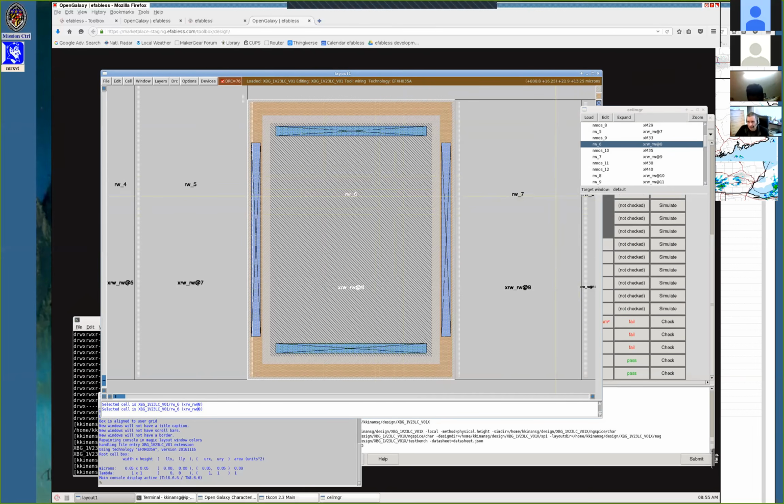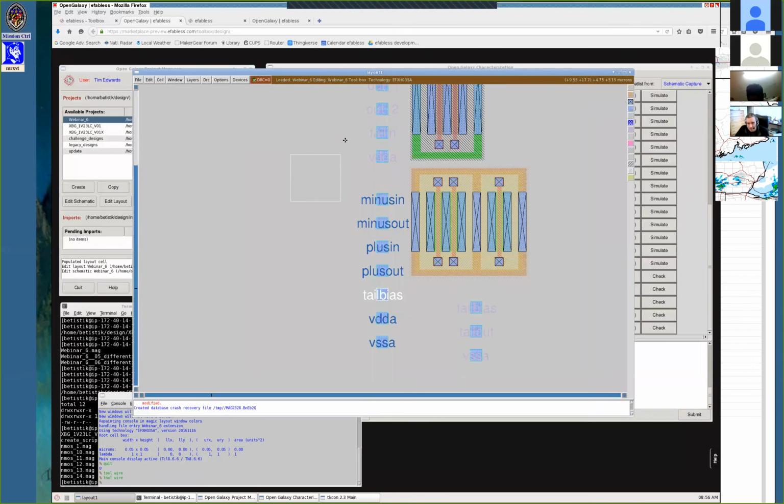And finally, I think the last thing I wanted to mention, as we are getting within a few minutes of the end of the hour, is the substrate ring. I did say that in this design kit you are not allowed to use the substrate or diffusion or poly layers. They're not something that you're supposed to be editing. However, there is one exception to that. Let me go back to this one. There's one exception to that, which is the diffusion layer.